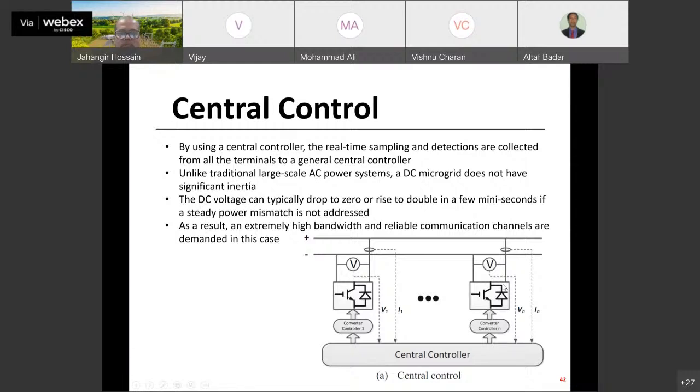Now, as I said, this is challenging because in the microgrid, in most cases, the devices have very low inertia or sometimes even zero inertia. When you have very low inertia and something happens, the deviation of all the parameters becomes quite high, and the system reacts very fast.